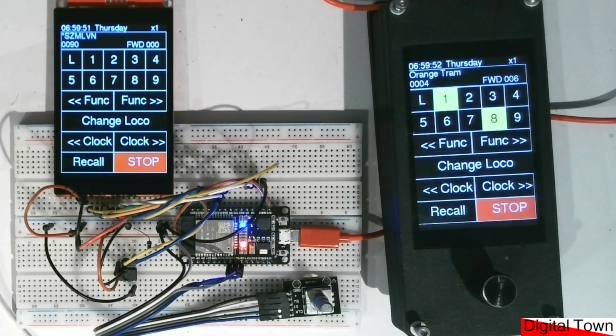and it's why I'm not going to go into the battery system in this tutorial, is that if the battery starts to go flat, if you are not giving enough voltage to the EEPROM, one of the dangers is when you send a write command to the EEPROM, it doesn't write anything and you finish up losing all your loco data. It's just something that I have discovered, so I'm doing a little bit of work for myself to figure out how can I sort of monitor the battery condition, and I might finish up putting a slightly larger battery in there.